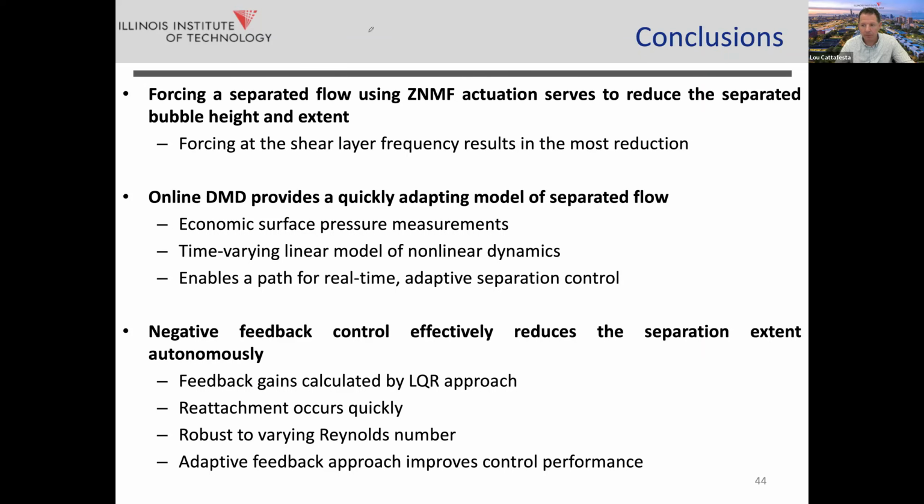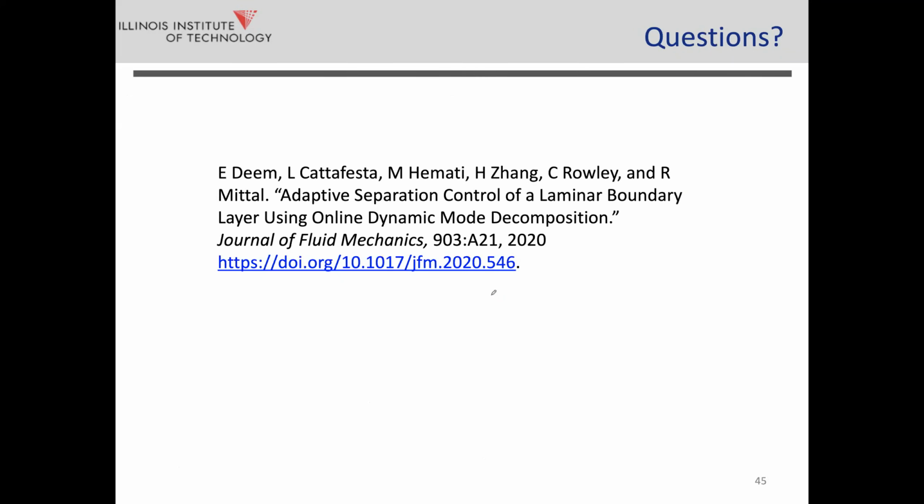Is this the same kind of physics of what you explained at the beginning, where you said the frequency is going to change if we control the wake rather than controlling a separating bubble? So whenever the bubble is small, then the nonlinear effects of the bubble are quite less dominant, and so we can kind of tame them down, or?